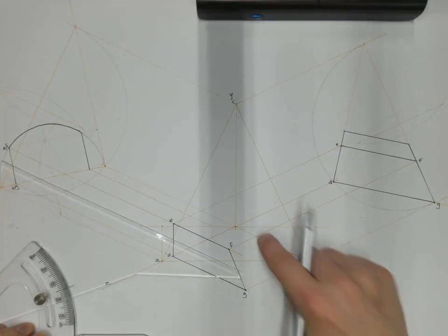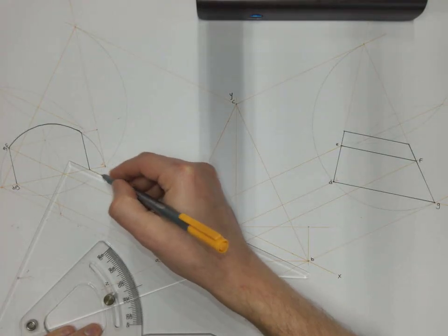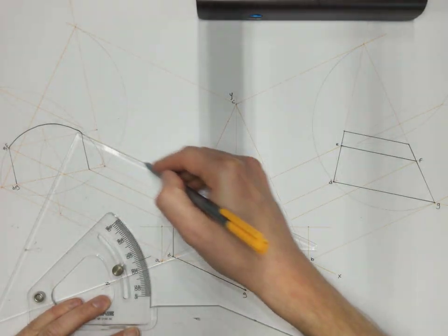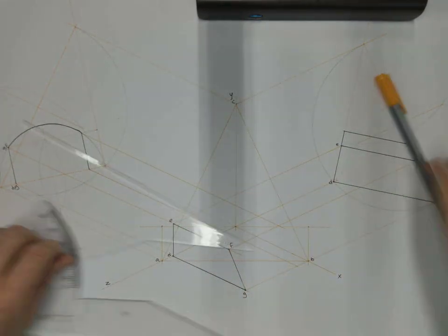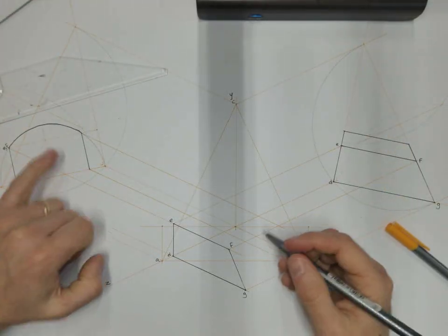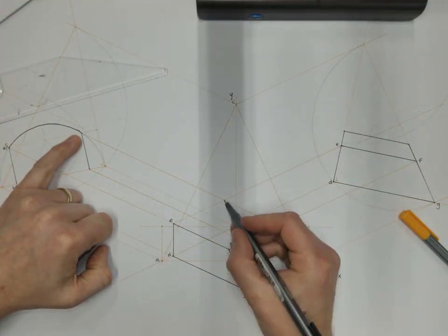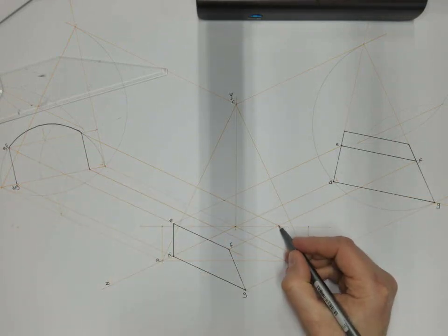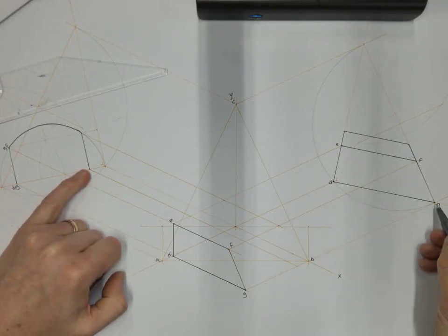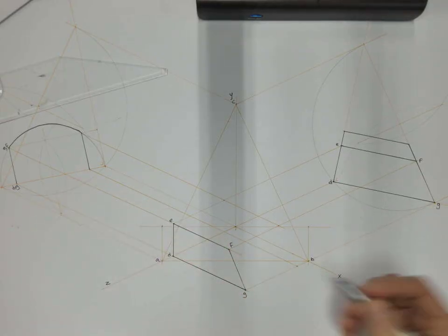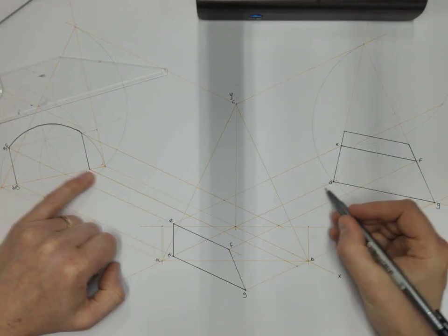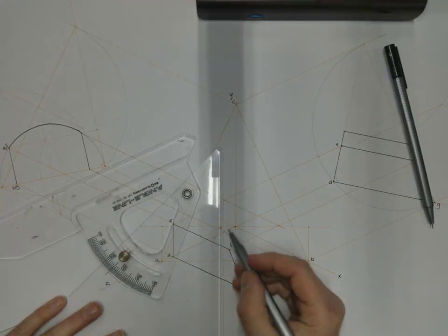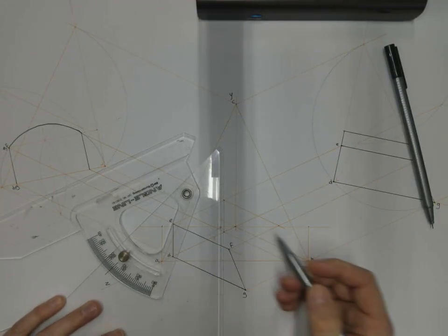So to draw the next part of this, I'm going to project down this point and the height of it. Okay, and where it intersects, the same point's coming down. So this line intersecting this line here, and this line intersecting this line there. Likewise, this point and this point here, and this point and this point here. I don't know how much of this is going to be visible, so I'm going to keep it as construction so I can come back and do it later.